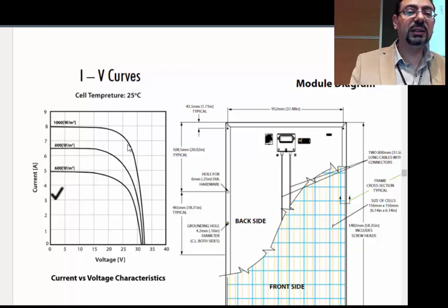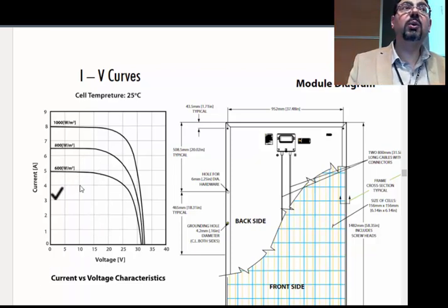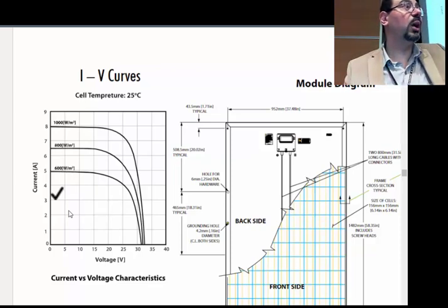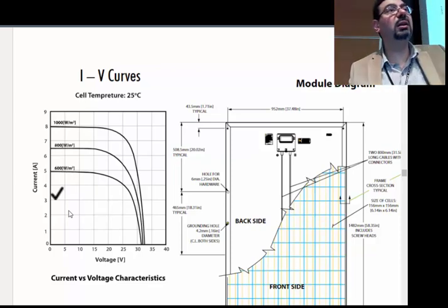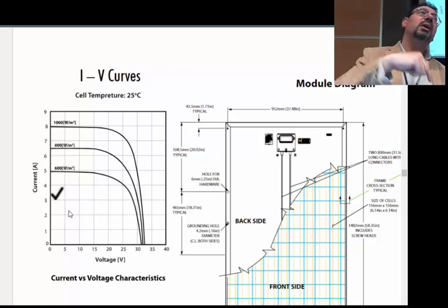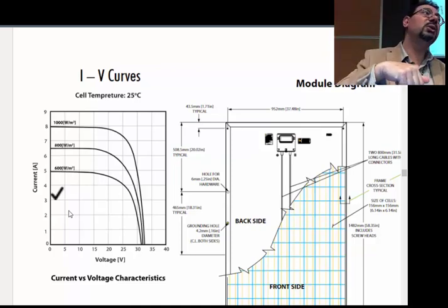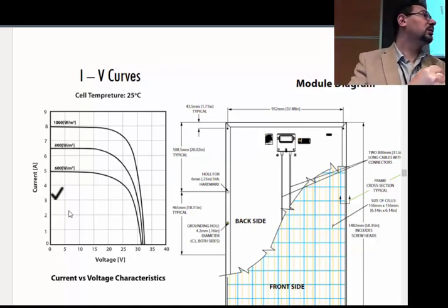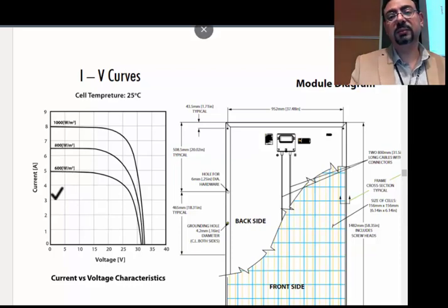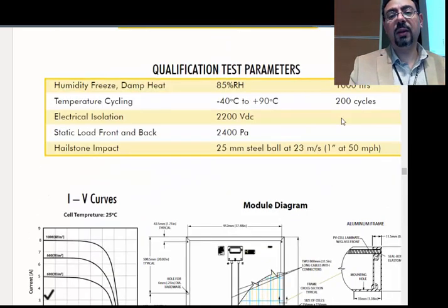So it's obvious that this equation, we can assume, is linear. The power output is linearly proportional to the incident radiation compared to 1000 watt. You give me the 1000 watt, I'll give you rated power. You give me 800, then I'm going to give you 800 divided by 1000 times the sticker rated power.